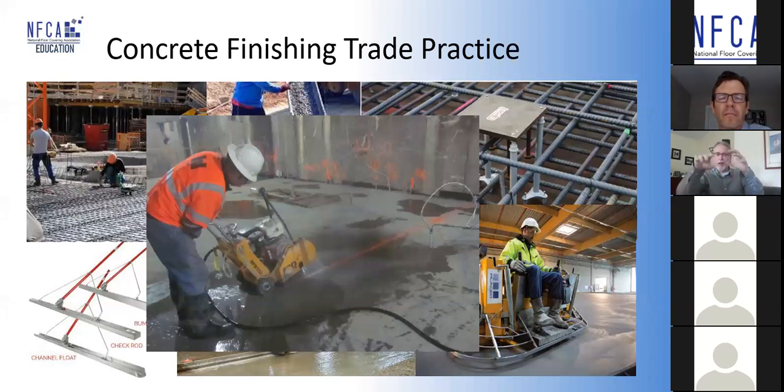A lot of times floor covering is actually installed, for instance, in an access hatch so that you don't see the access hatch. But it doesn't do much good if the access hatch is set too low or too high, because now you've got a different kind of bump in the middle of your floor that you can't correct. They also saw cut in the contraction joints. They also fill those with particular sealants. Something else to coordinate: if there are sealants that are not compatible with flooring materials, it'd be a good time to raise that point. And they also coordinate with the next trade.